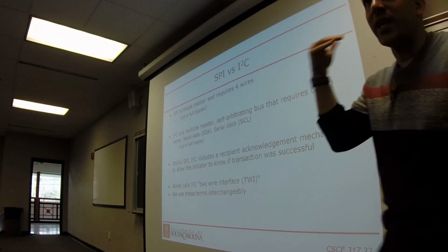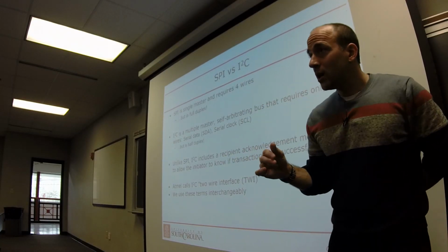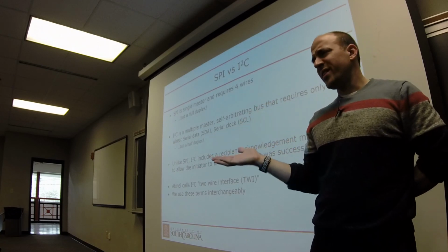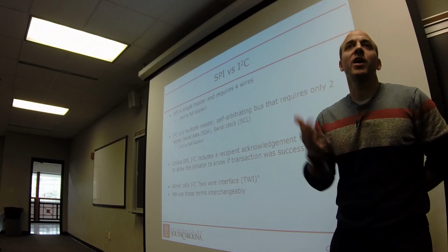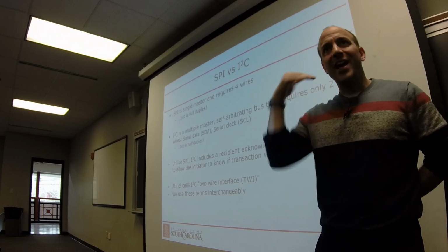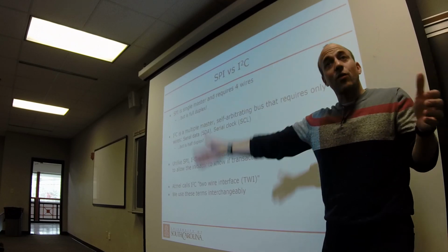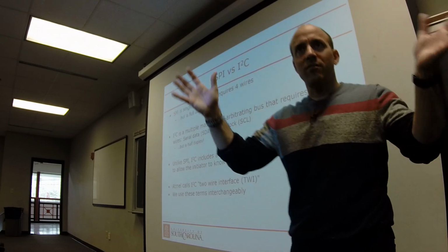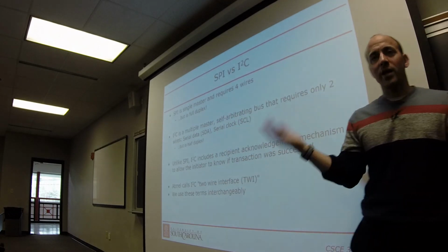So if you read the INT1_SOURCE register on the accelerometer, what's it telling you? Well, it doesn't matter. You just ignore whatever it is. But reading it is what acknowledges the interrupt. It's the way your code tells the accelerometer that, okay, I understand data is available and I've consumed it, so now stop trying to interrupt me, right?